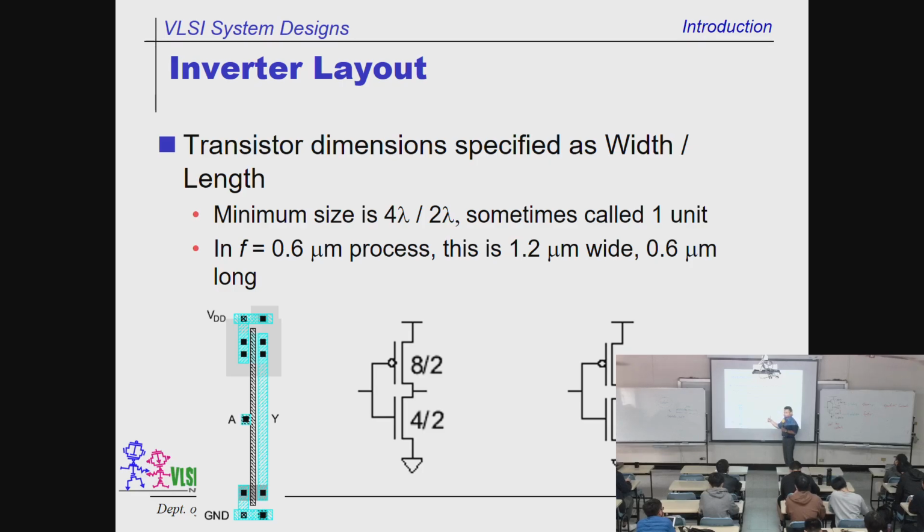So very informative. From this figure, this is a layout, we have the picture about the size of different transistors. And why is the size different? Because there is a demand behind that. It is called the equalization of speed, charging and discharging speed, or charging and discharging delay. We want to do that. Understood? So in the inverter design, you might be curious why the size is different. That is the reason why.